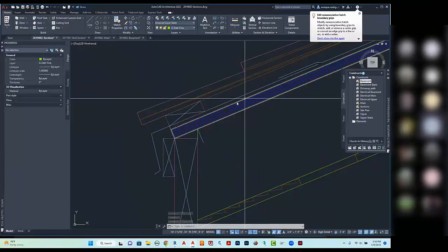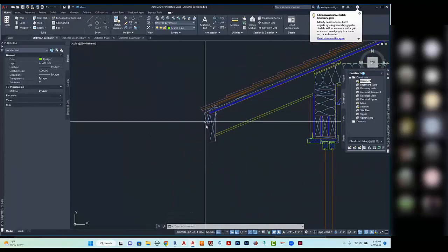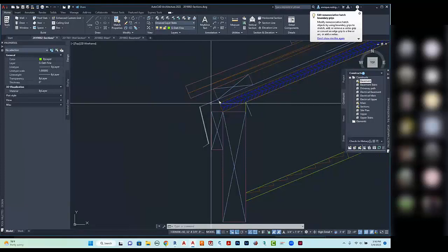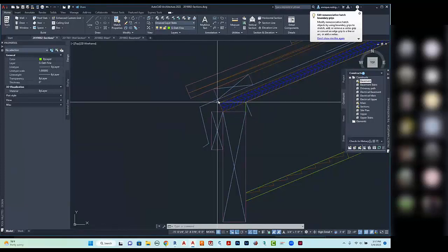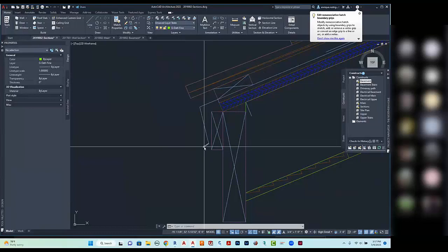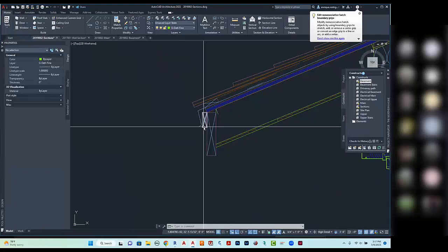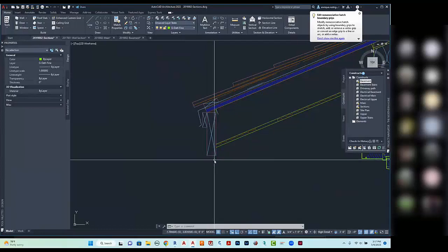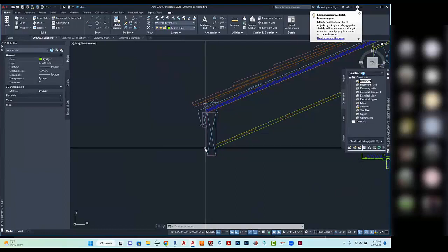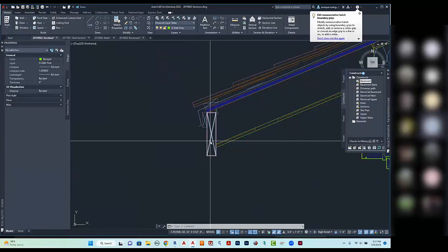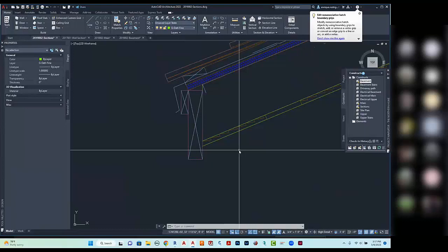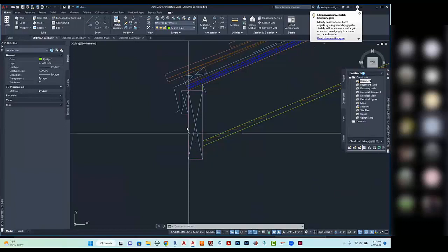And what it does, it provides a waterproofing condition here with the metal that doesn't allow any water to seep in through here. Located like this with a slight angle at the end, so it causes a drip edge that will not run down your fascia board in here. Now, fascia boards can be composites of many different materials or pieces of wood put together, depending on how fancy or simple you want to be.